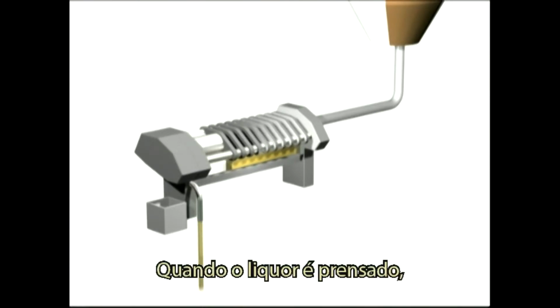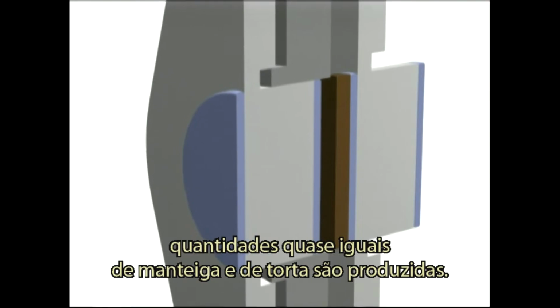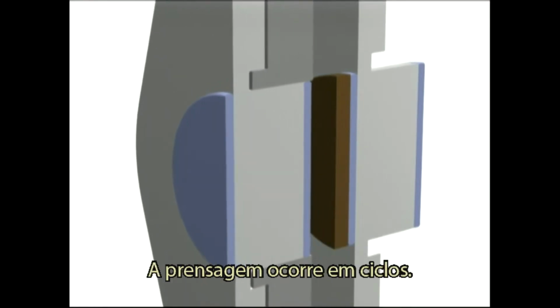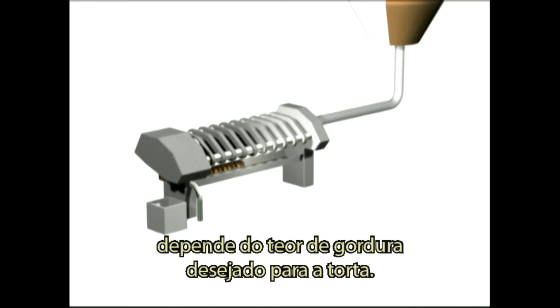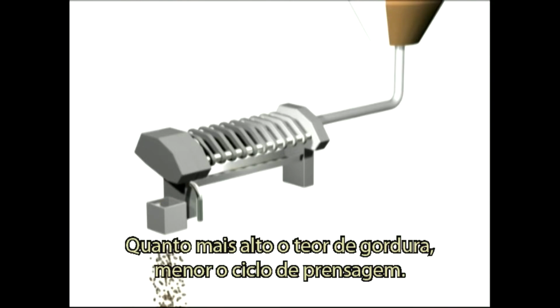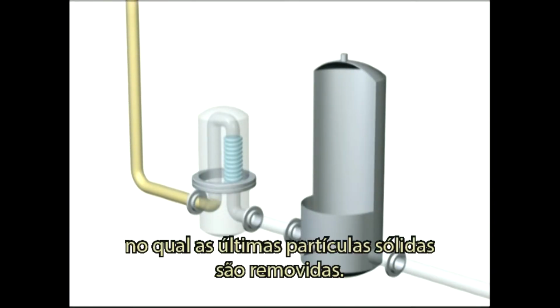When the liquor is pressed, approximately equal quantities of butter and cake are produced. Pressing takes place in cycles. The length of the pressing depends on the desired cake fat content. The higher the fat content, the shorter the pressing cycle. The butter passes a filter where the last solid particles are removed.